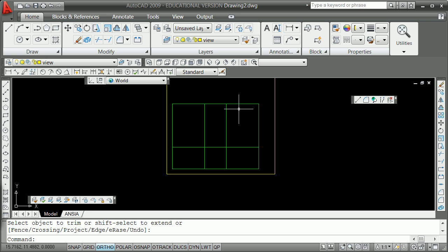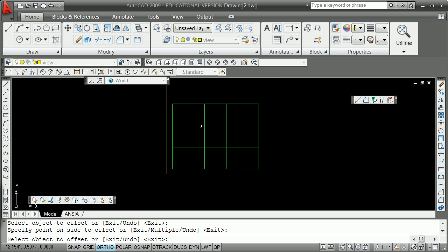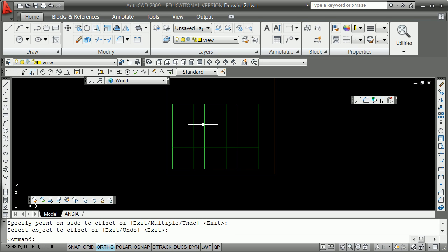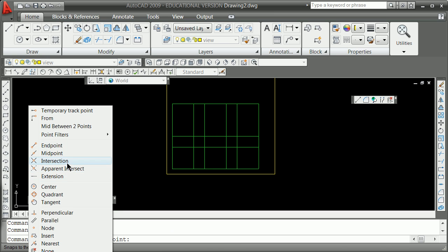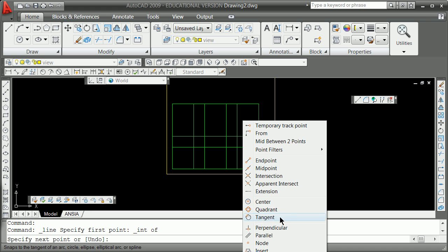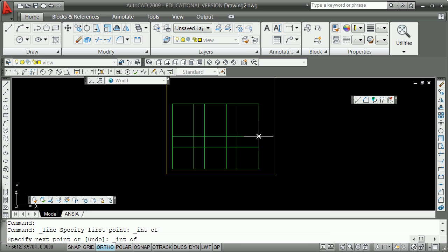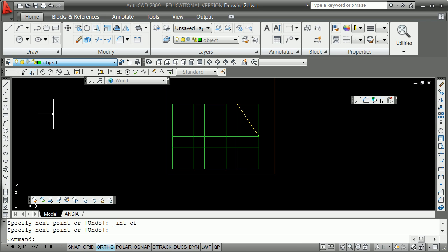You know that middle part is not there, but offset 1. Those are the 2 going on there, and then it's offset 1 off of here, offset 1. Your eye will start to get confused in a little bit, but if you do a line from the shift right click at the intersection of that, shift right click to the intersection of this. Remember, because we were doing offsets, we were okay, but this is actually a symmetrical piece, so learning to do a center line in there is a great idea, but instead I'm going to learn to